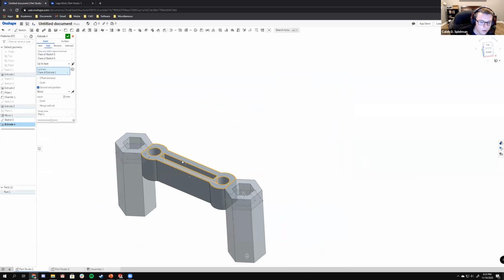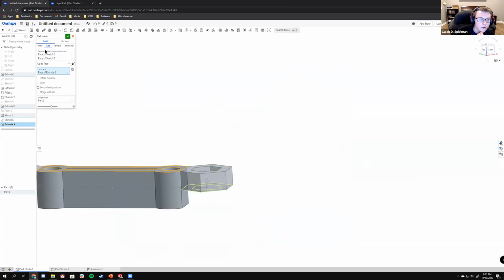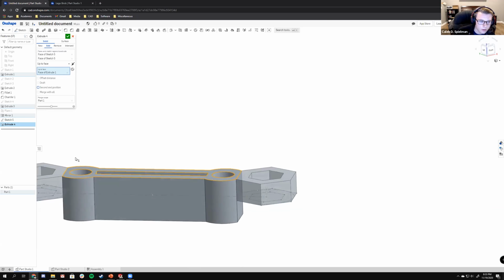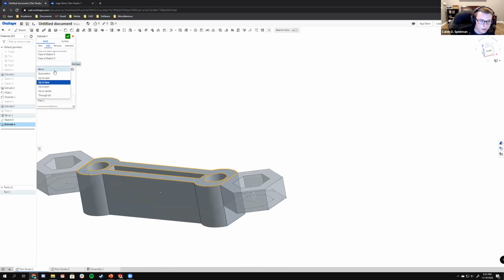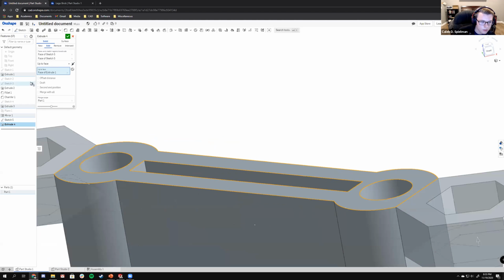Second end position. This is just the same contours, but in the opposite direction of the one that you chose. So let me repeat that. So we have extrude. We have a solid for now. Add. I picked those 2 contours. They'll pick it automatically, however, often. Instead of doing blind, I did up to face and selected this face so that they'll end at that face.